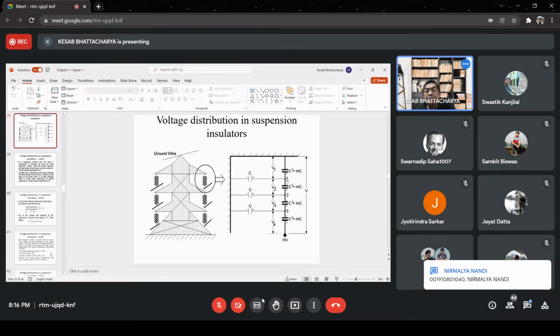So here, the charges may come from the bottom and enter node 1, but whatever amount of charge enters node 1 will flow to ground via the mutual capacitance and ground capacitance.